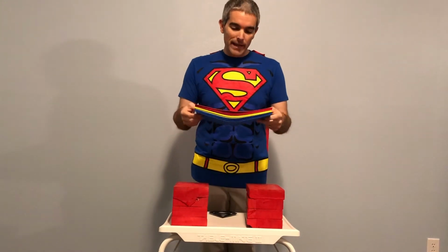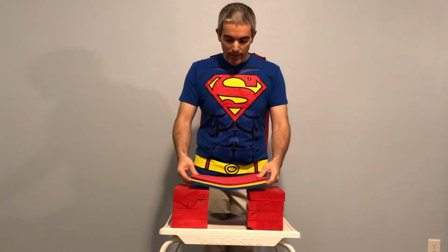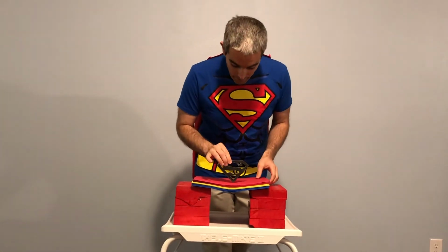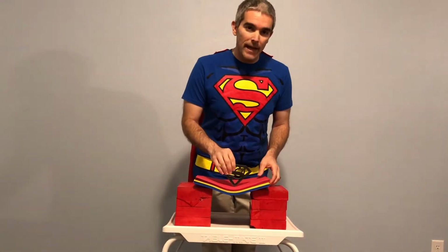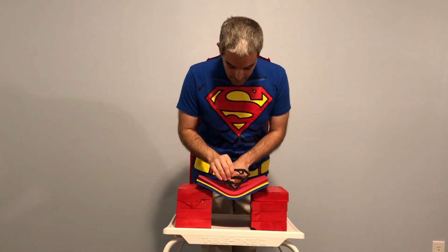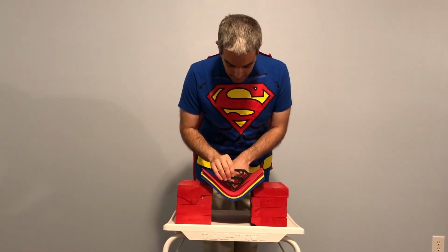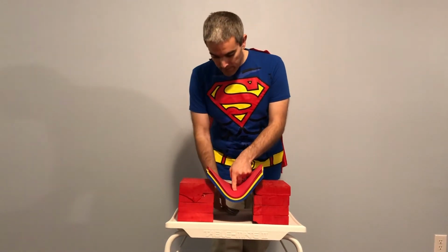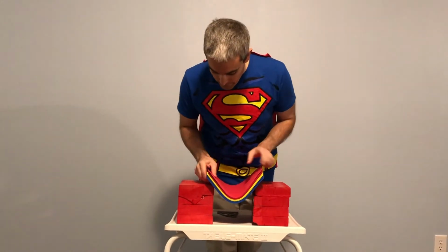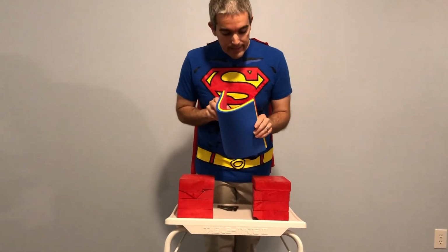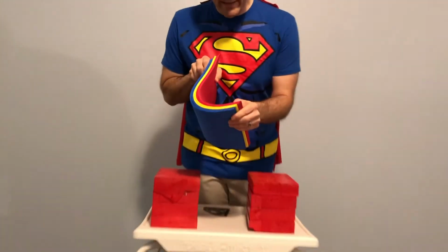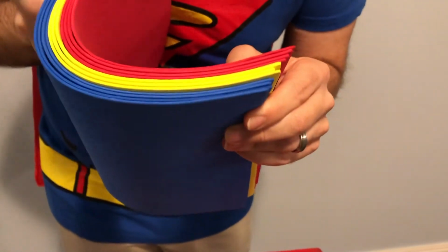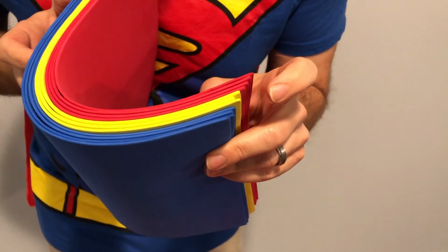So if we take a look at this beam and I go ahead and apply a point load on it, now I'm going to exaggerate the effect, so I'm going to just keep displacing it. As we push down, we see that all the layers resist that force. But you can see at the ends, we get some separation. The layers of the system separate in almost a staircase manner.